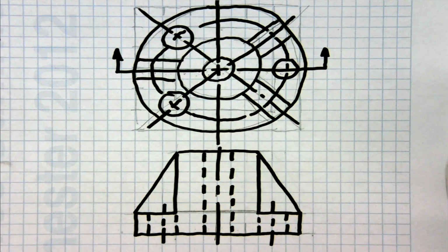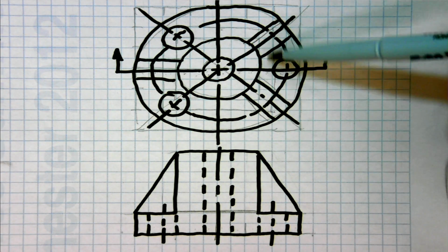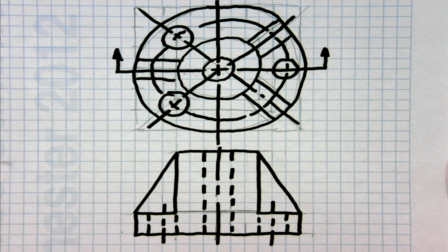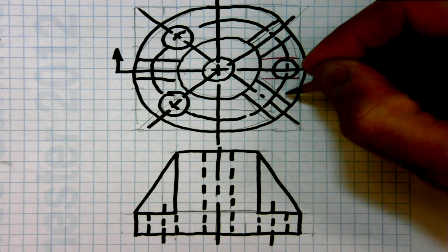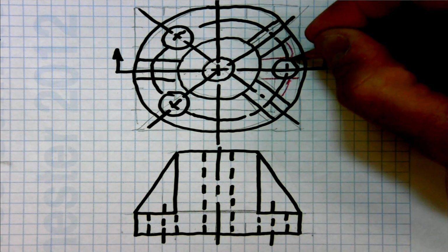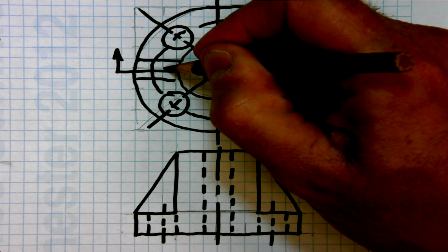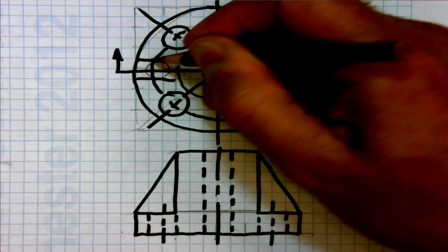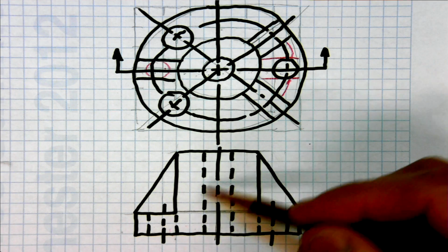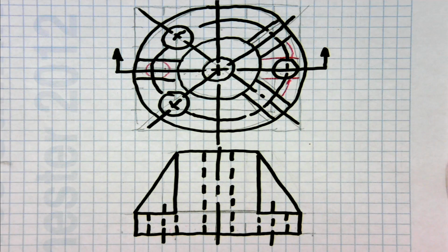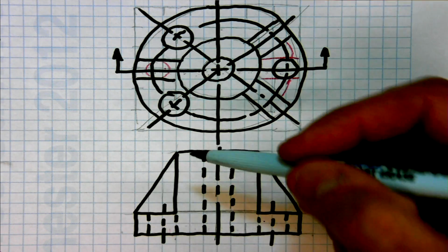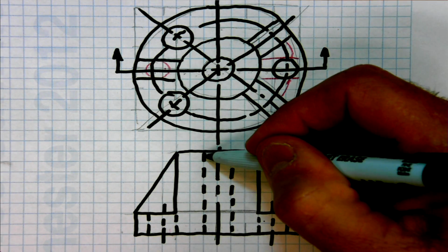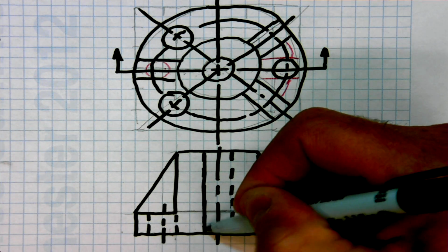Now what happens? It acts as if these two support features are moved into this position that I have here in this colorish red. So it acts as if these things are moved into this position. Moved to there, that one's moved to there. It acts as if these holes are moved into the position right over here. So when you cross-hatch it and cut this thing open, notice that these features have been rotated. The rib is rotated into this position, the holes are rotated here, and I've cut entirely through the object, thus exposing the limiting element of this cylinder here.